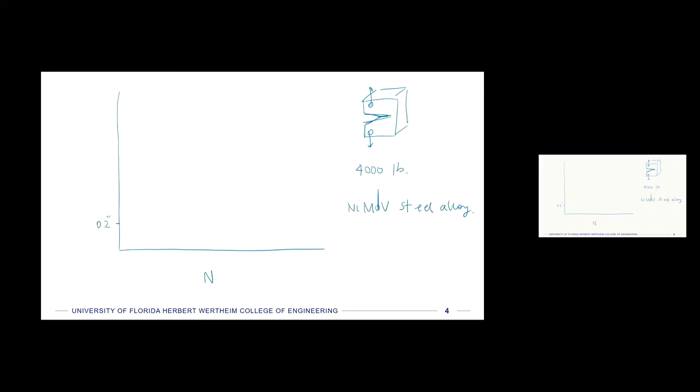So it's a known crack length at the beginning, and then this thing is just going to be cyclically loaded again and again, and the crack length as it propagates across is going to be measured. So the crack opens up, and at, let's say, 160,000 cycles, that's the upper limit of the x-axis, the crack opens up to 1.3 inches. So that's one data point up there.